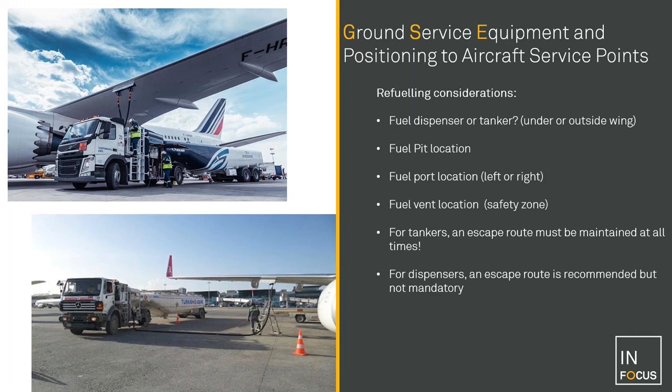Some Airbus models, especially the smaller A320 series, also have the port, depending on the order, whether it's an optional thing, but a lot of companies still have the fueling possibility on the left for those smaller aircraft. If you know that the airline has this option, it can relieve a lot of congestion on the left side of the aircraft where baggage loading, catering, and other things are happening in a short space of time. It can be a great advantage in your planning scenario to be able to fuel also on the left-hand side of the aircraft.